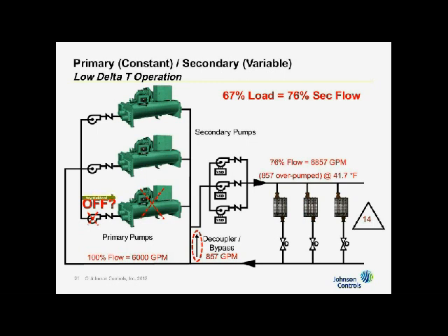Now that in itself is not a bad thing because you remember myth number 1 from last time. But what is bad is if you don't have optimal control and variable speed drives on your condenser water pumps and everything else, and you have all the optimal control going on, then it will cost you more energy. So that's another problem. There's more energy in the plant.